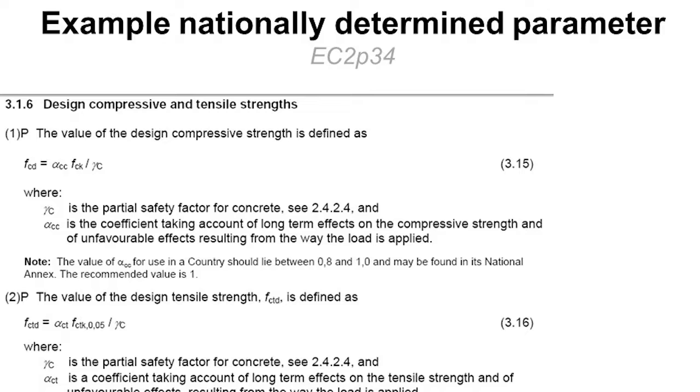If we made a batch of the same concrete all the time, we can't always rely that this concrete is going to be 35, so we divide it by a safety factor, and that's the material that we design with.